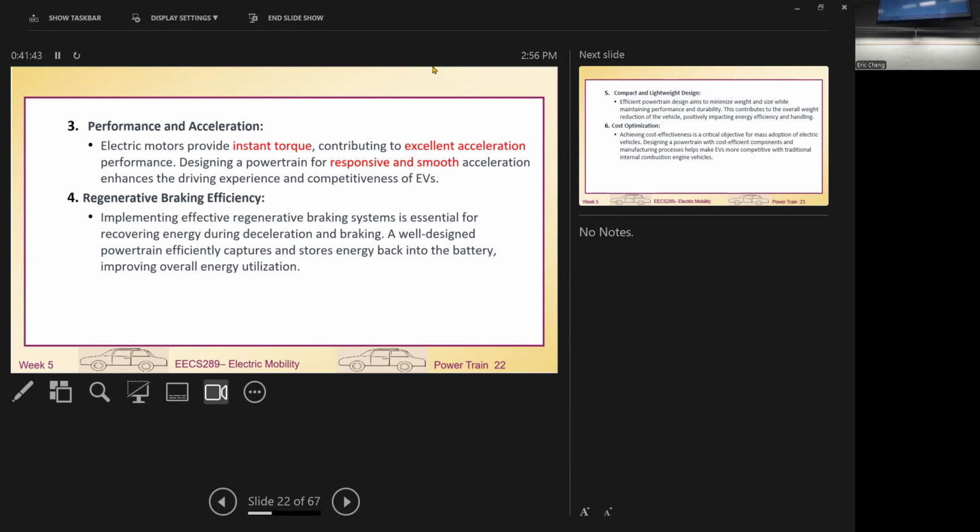And then regeneration. Regeneration is getting more important nowadays because for a good performing vehicle, we need really good power regeneration so that any energy from braking or going down the hill can be returned to the battery. But usually a motor has 80% or 90% efficiency, even 95%. That can be quite common for motoring. But for power regen, a motor may not be designed well for power regeneration. So if you want a motor to have good performance, you need to tailor-make or design a motor for the side you want more performance in, motoring or regeneration.